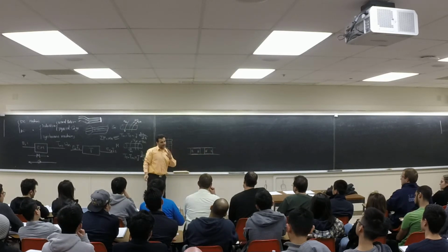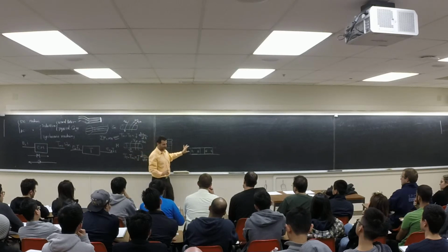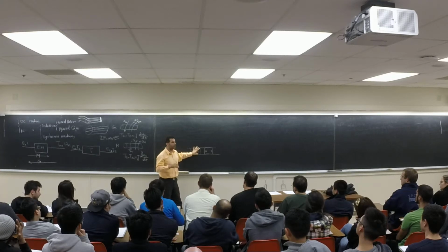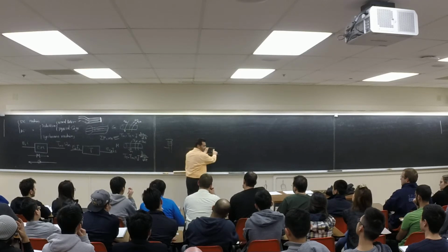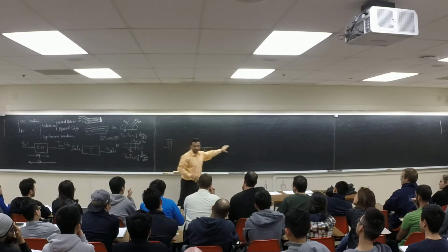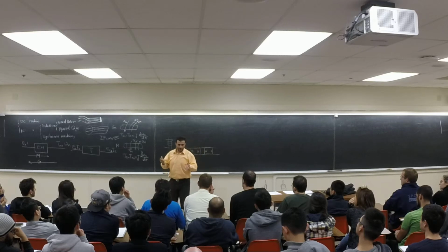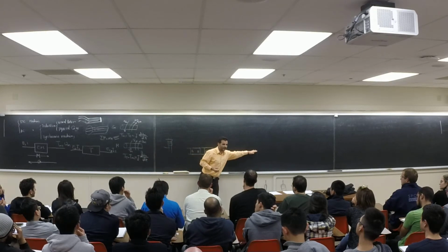Now, this is the concept of a synchronous machine. Think about it: we can start to move this one with some speed, slow or fast, to bring it close to this magnet, and both of them start to move together. When you move this one, that one is also going to move. Don't go too fast or too slow, which would create a problem. So if these two magnets move at the same speed, it is called a synchronous machine.